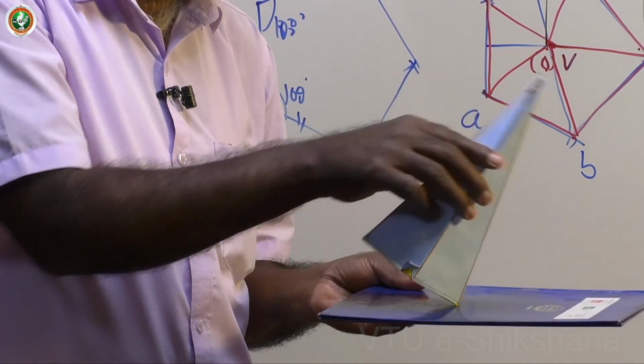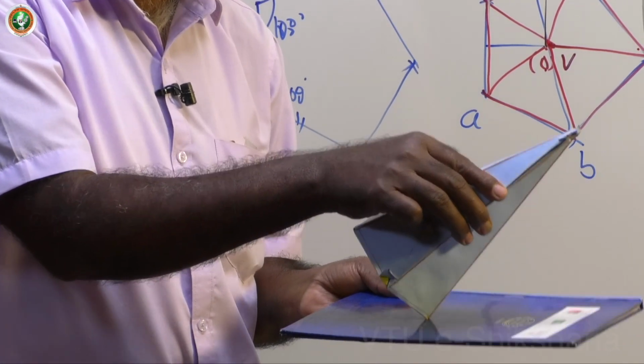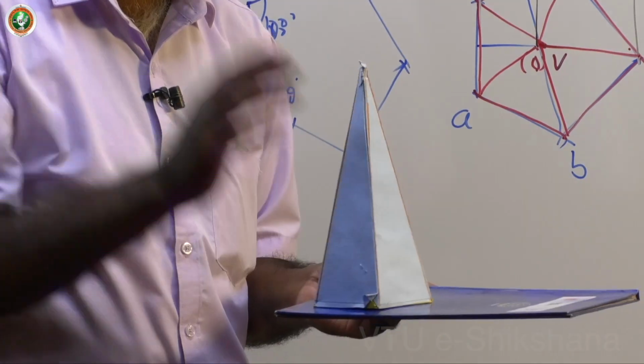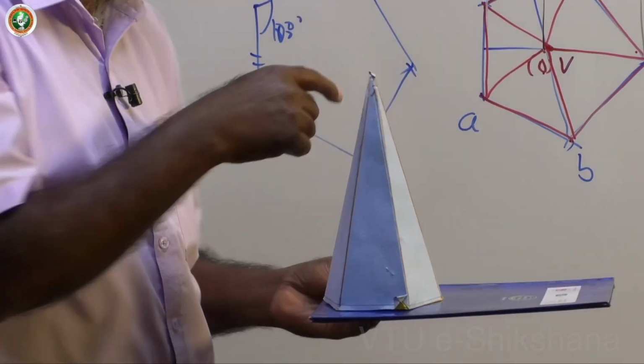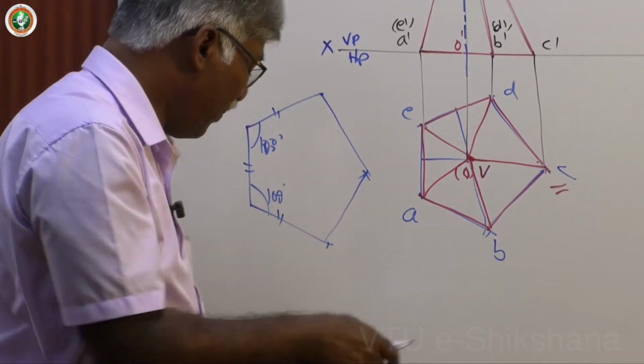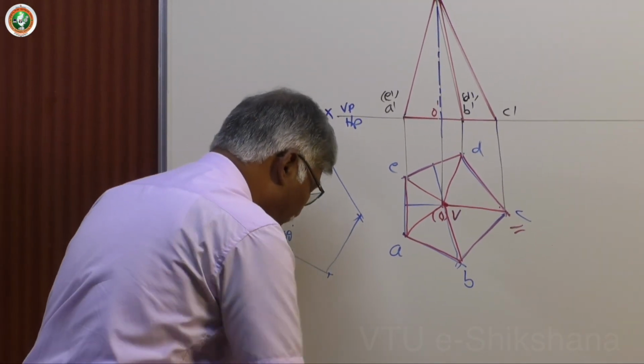First position, second position. So, initial position is the axis inclined to HP. So, you make it perpendicular to HP to get true shape on HP, fine, you are getting the top view as true shape. Now, dimensioning and all is common, you must do it accordingly.